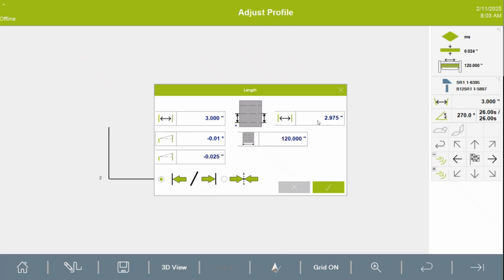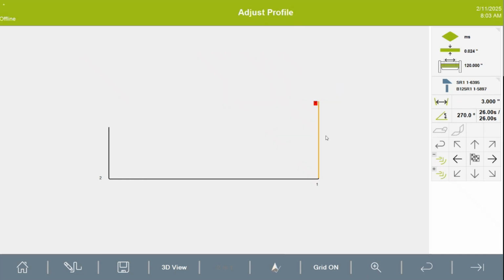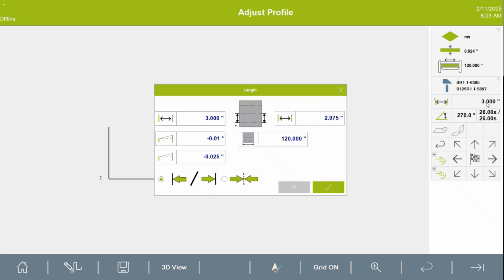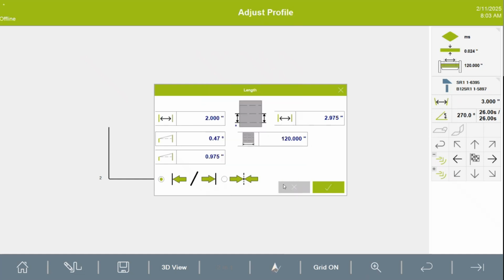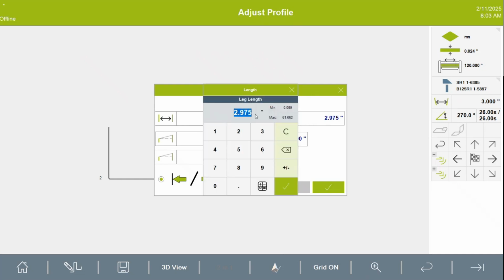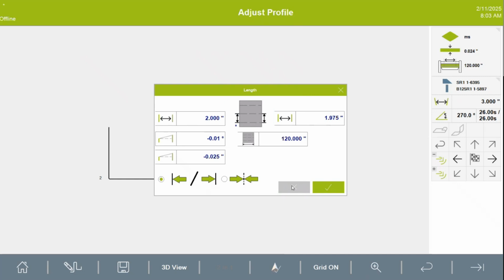All right. So just to review real quickly, if you need to change the length of a flange on a part, you can modify these parts. Click here just like you always do, and you tell it the new size. However much you add or subtract from this side of the part, you must also add or subtract that amount from this side of the part. Okay, that's the way you can do this.